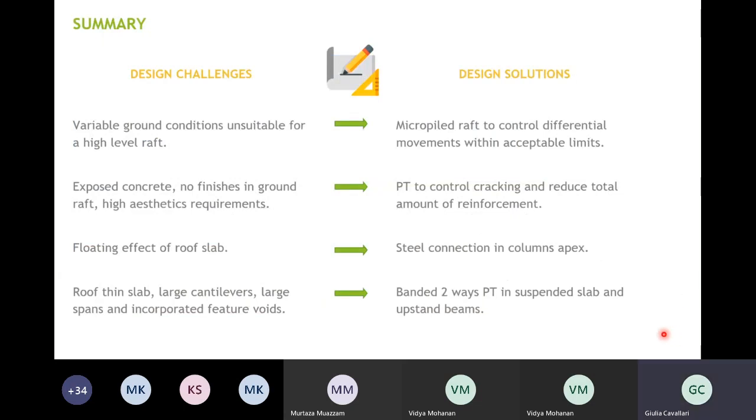So in summary, we had a set of design challenges and we found design solutions. The variable ground conditions were not suitable for a raft or for individual pad footings. Therefore, we decided to use a micropile raft to control the differential movement and limit the settlement.